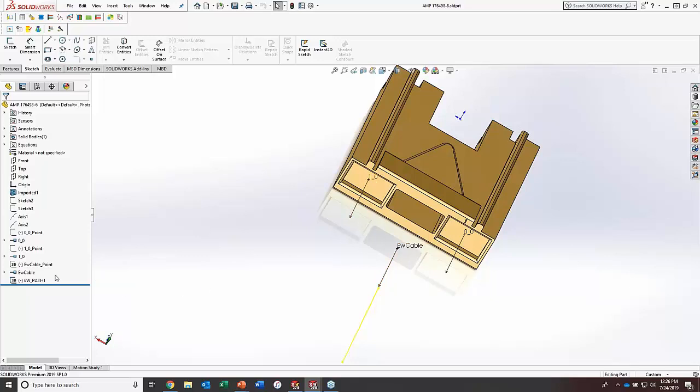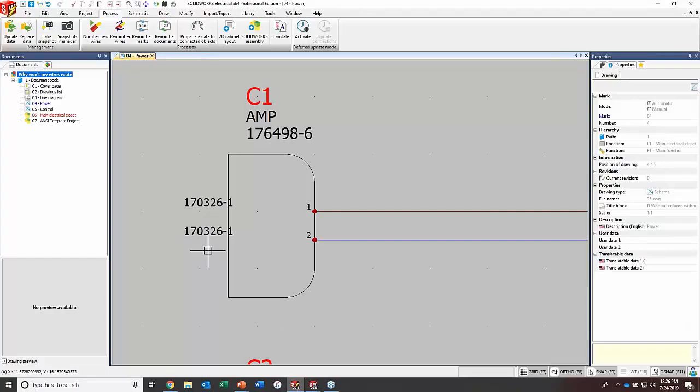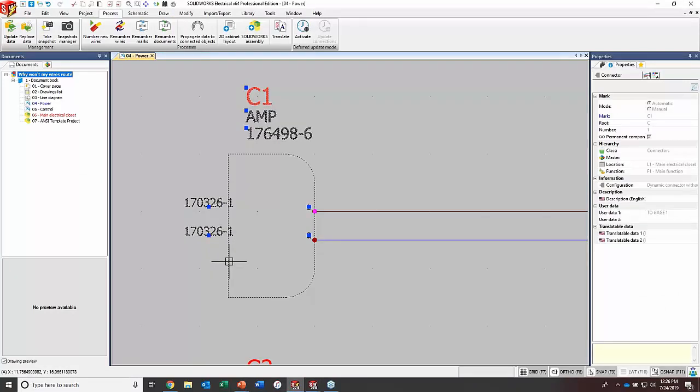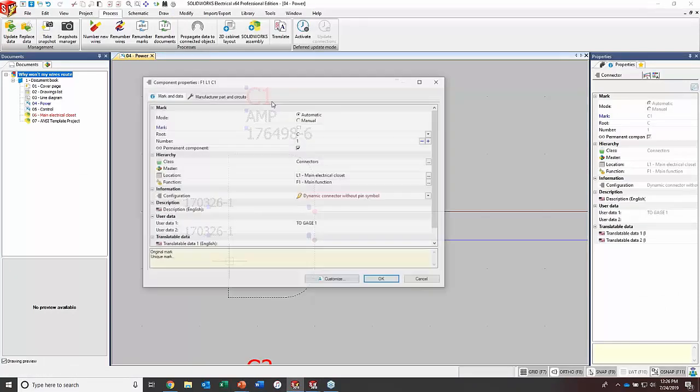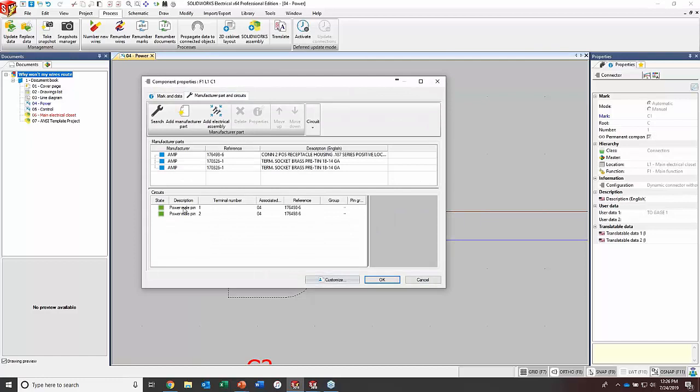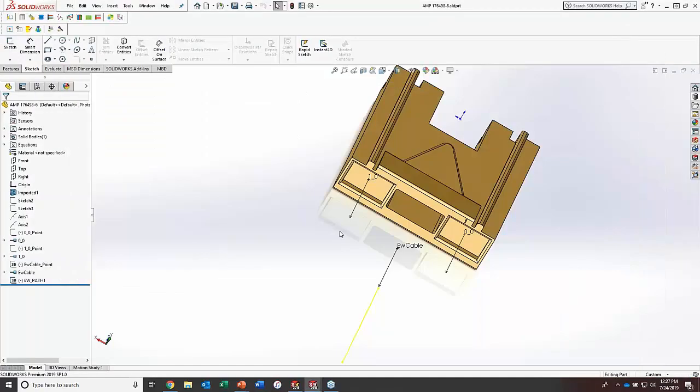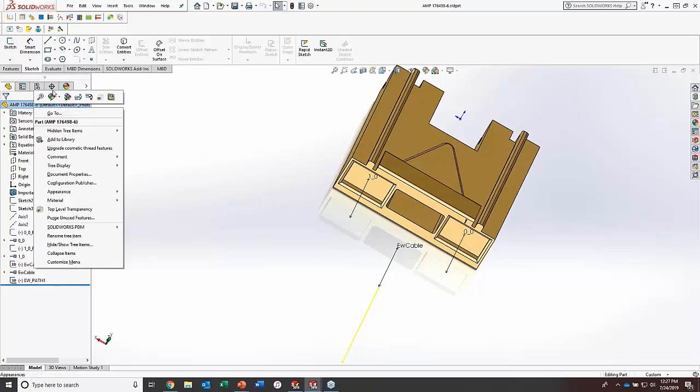Once you have those 3 points, you want to make sure that they are matching up with what you see in your SolidWorks schematic here with that true component of those values that we talked about for these 2 connection points. So again, 0, 0 and 0, 1 we saw from power, these 2 power pins. Once you have those 2, you can then place that into your assembly.